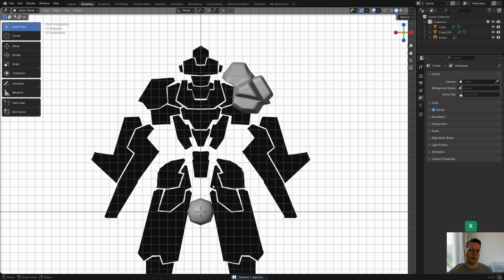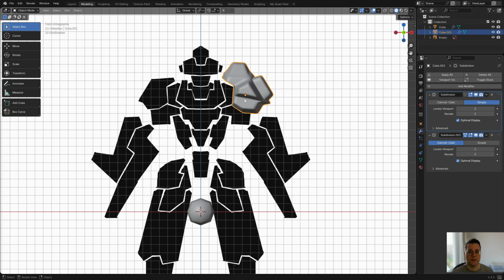Let's say I created a really messy, quick sketch with a pencil on a napkin or whatever, and it's just going to be too rough for Trace Image to Grease Pencil to turn it into a nice, clean mesh. In that case, I would recommend using this technique with just this cube with these 2 modifiers and duplicating it and then adjusting it in X-ray mode. Just box modeling, in other words.